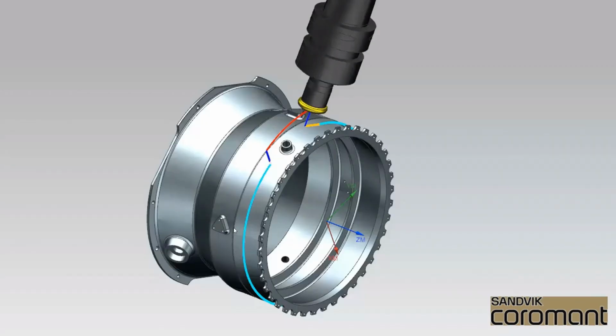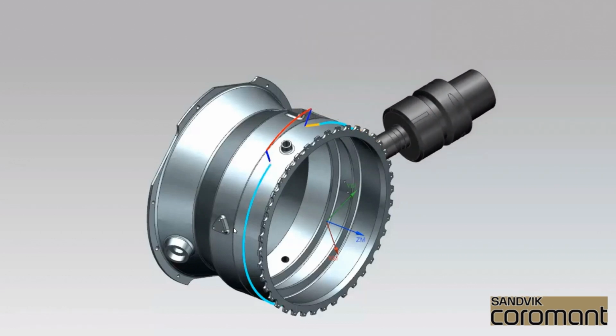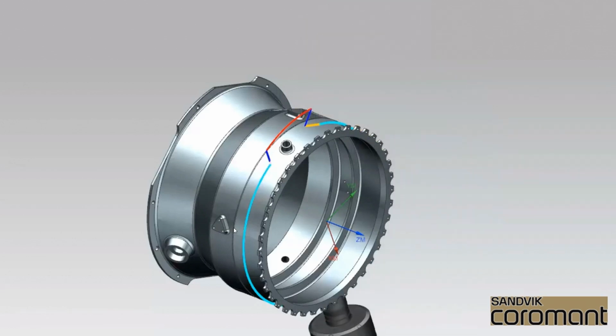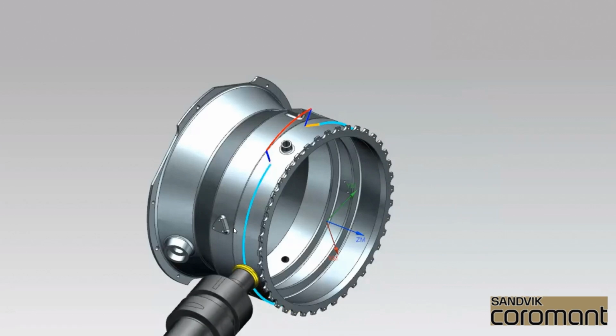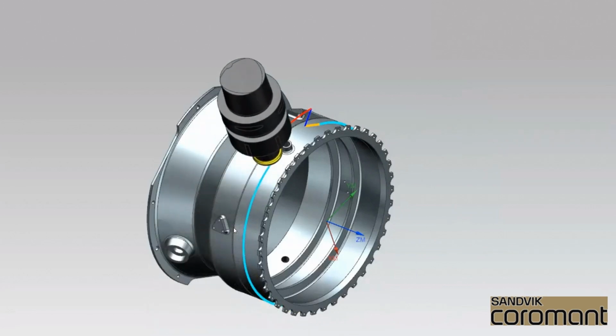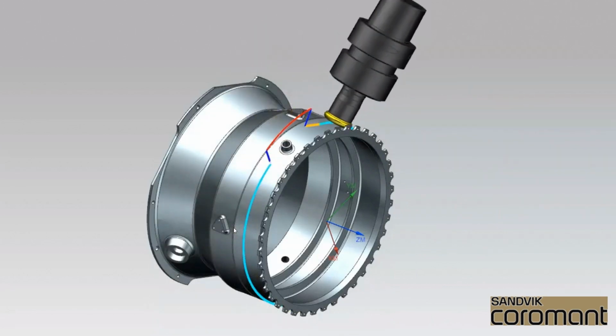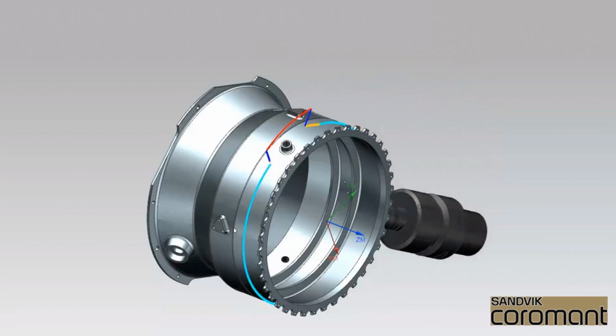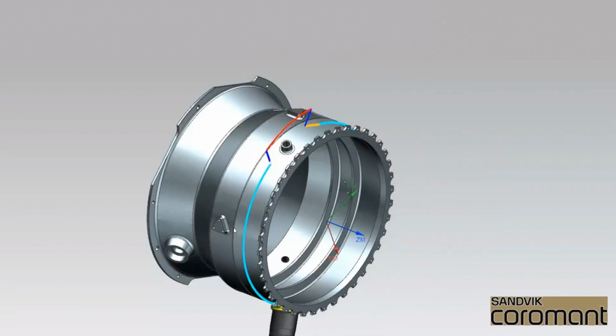Here's just an example of it programmed in CAM software. So kind of typical, you'd see the tool path going around. And in this particular example, it's just trying to miss that boss that's in the middle. And that's why it couldn't be turned. You had to mill all that out of there because of that boss in the way.